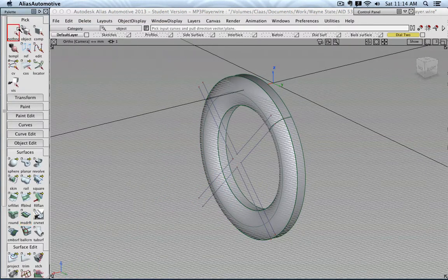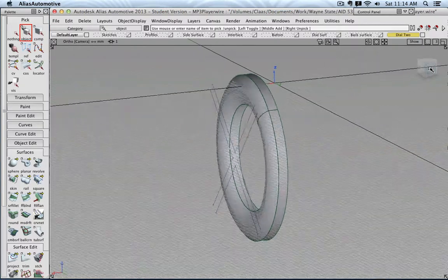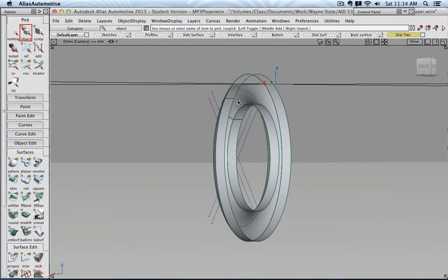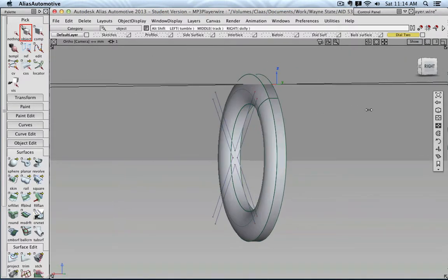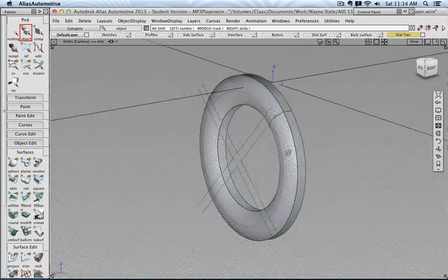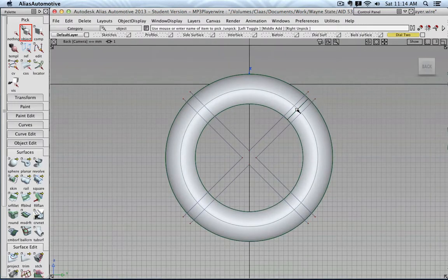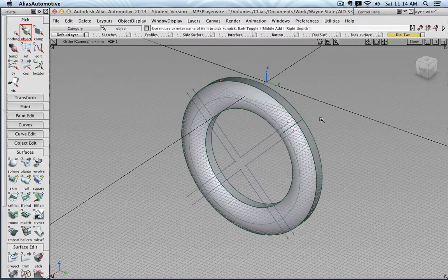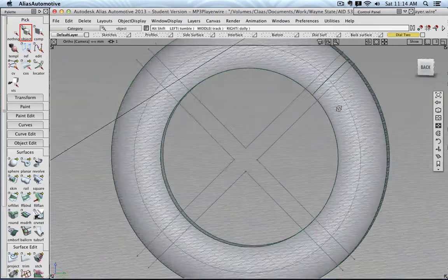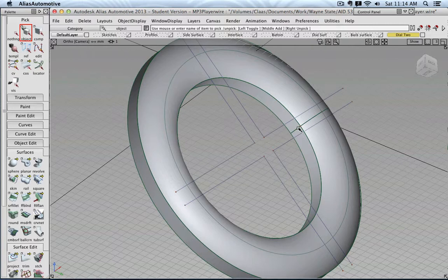And you see that this way I created my surfaces for the button, basically, by only sampling the edges from the Revolve surface we created. You can also see now that here is the thicker green line, which means that is the surface edge.